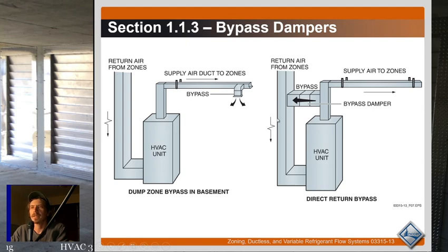And then the next thing you know, everything starts to drop off. Airflow drops off and power usage drops off. That's because if you've got a motor, a pump motor or a fan, and you're deadheading it, it has nowhere to move that air. It has nowhere to pump that water. All the water is staying in the impeller, or all the air is staying in that squirrel cage. It can't do any work. There's nowhere for it to go, so it just freewheels.